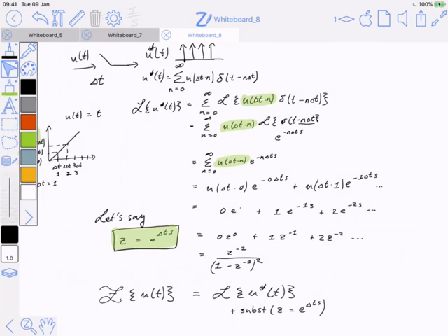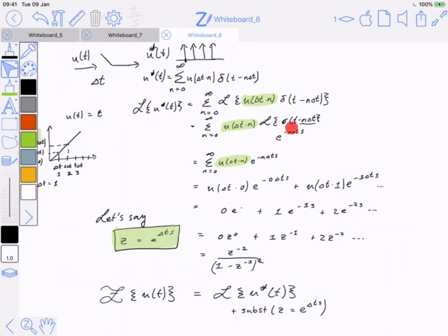And so keep in mind that that Z comes from, so this definition of Z, compare that to this part here, which is the Laplace transform. It's a time-shifted delta, right? And so you can say that a Z of a particular power corresponds to the value of a signal at a particular moment in time, a number of time steps back.